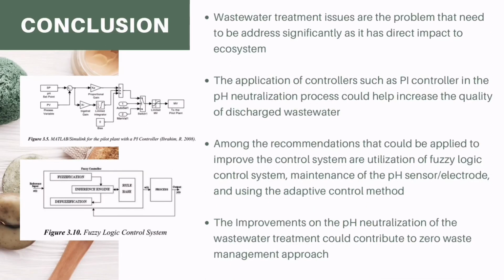In the conclusion, the wastewater treatment issue are the problem that need to be addressed significantly, and it has direct impact to the ecosystem. The application of the controllers such as PI controller in the pH neutralization process could help increase the quality of the discharged wastewater. Among the recommendations that could be applied to improve the control system are the utilization of the fuzzy logic control system, maintenance of the pH sensor, and using the adaptive control method. The improvement of the pH neutralization of the wastewater treatment could contribute to the zero waste management approach, as it minimizes the threat towards the environment, including the aquatic and human life.